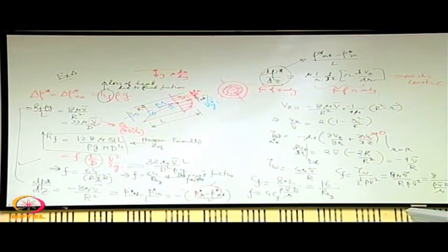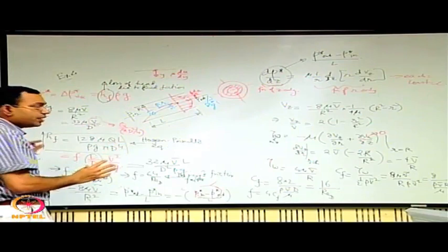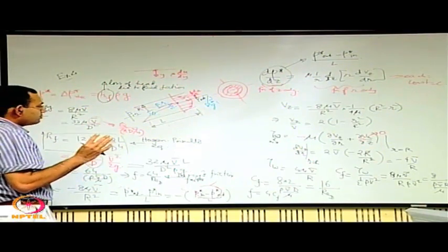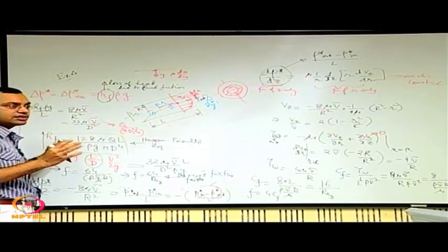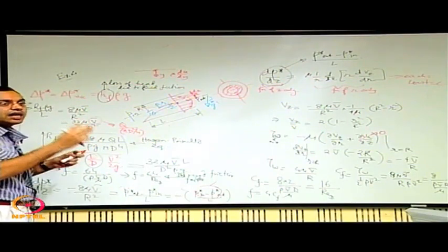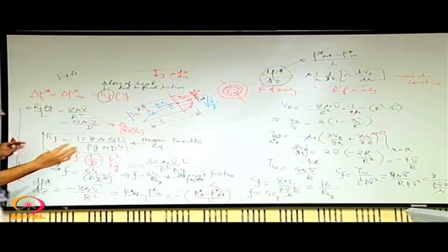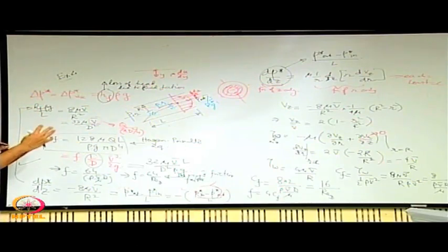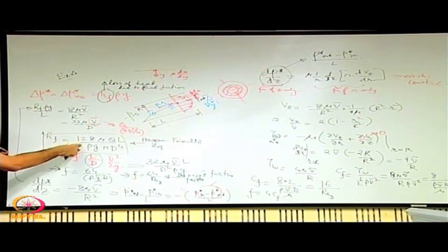So now we have a clear idea that if we have flow through a pipe, there is a head loss. The head loss is because of the viscous effects in the flow, and you require a driving pressure gradient. The driving pressure gradient is to overcome an energy loss. The energy loss may be expressed in terms of a head, and that head is given by this expression.